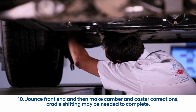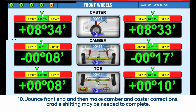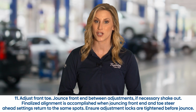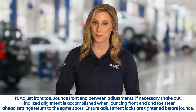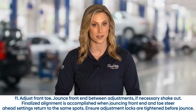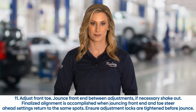10. Jounce front end and then make camber and caster corrections. Cradle shifting may be needed to complete. 11. Adjust front toe. Jounce front end between adjustments. If necessary, shake out. Finalized alignment is accomplished when jouncing front end and toe steer head settings return to the same spots. Ensure adjustment locks are tightened before jounce.